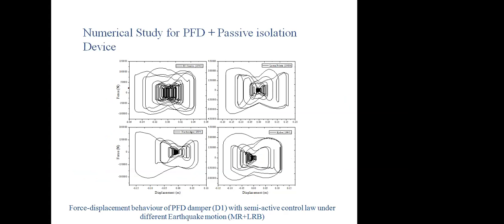The post deformation behavior is just like a butterfly type. Okay, so automatically, if the area of the post deformation loop is higher, it will produce a huge amount of damping. The friction damper loop is just a single right-angle box, whereas this one is like a butterfly shape.